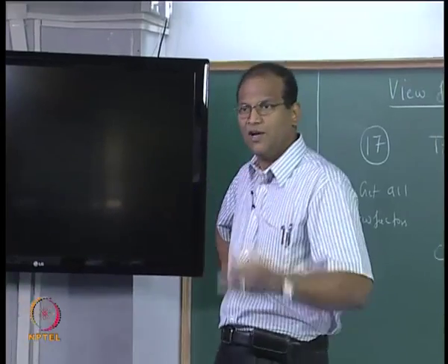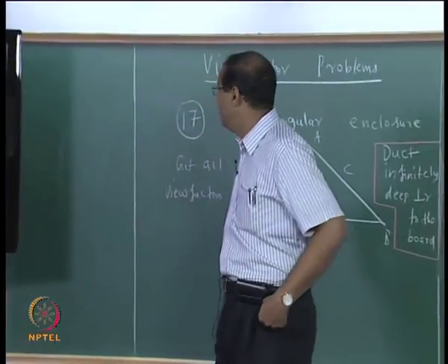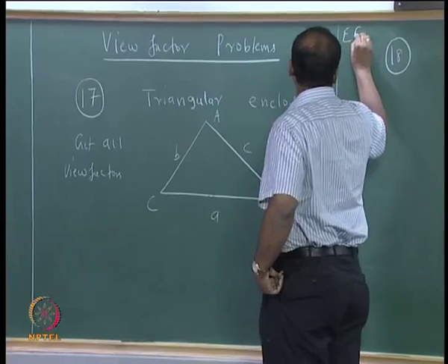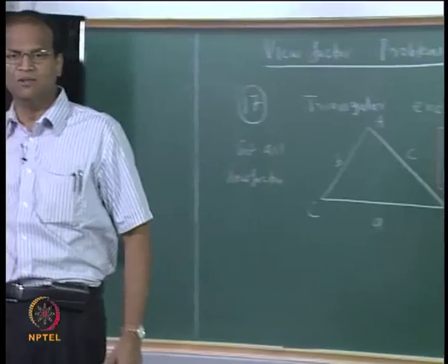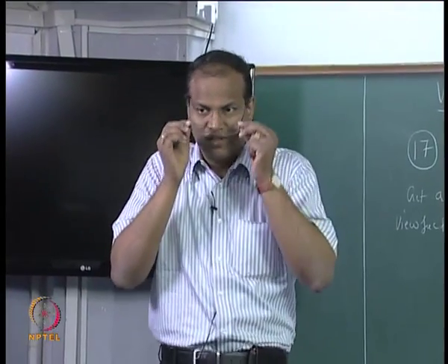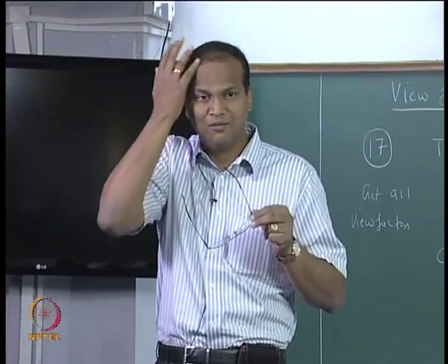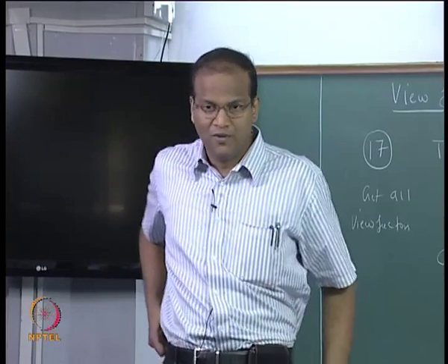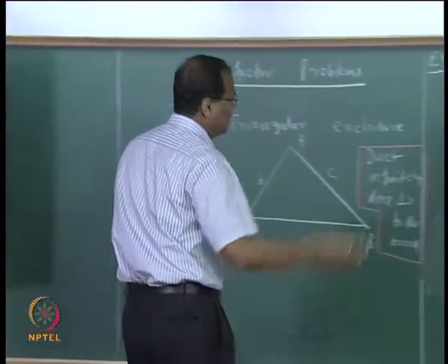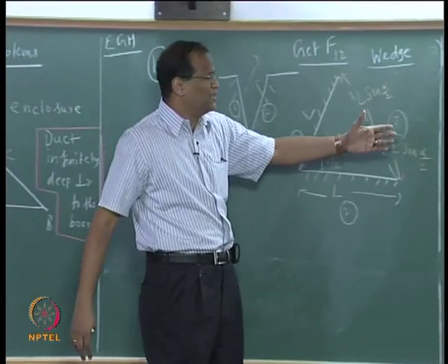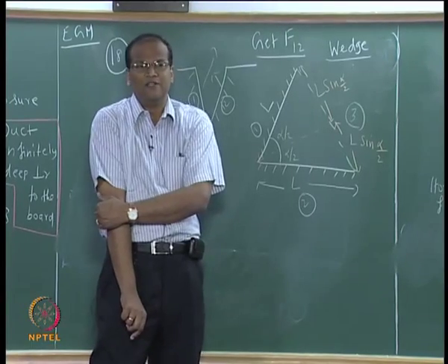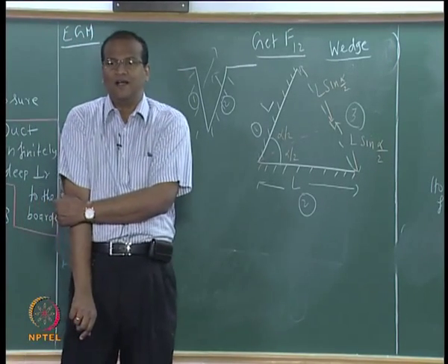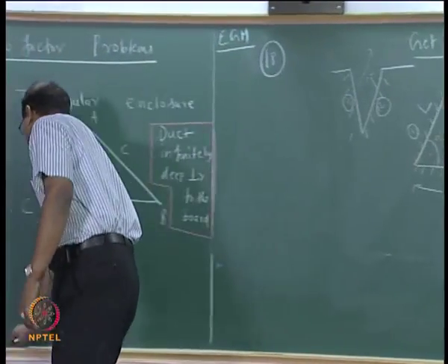What I have just explained to you is a 2-minute course on a very important topic called EGM, entropy generation minimization. That is a well established field by itself. Professor Bejan has written a book on entropy generation minimization. So there are umpteen ways of optimizing. Optimization in heat transfer does not always mean that you want to maximize the heat transfer. Sometimes you also want to minimize the pumping power, or you want to have a trade off. So we will stop it at that stage.